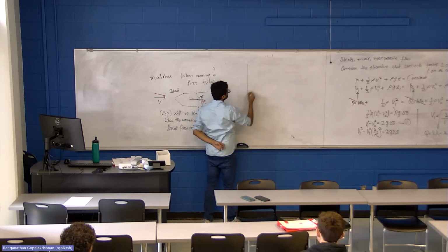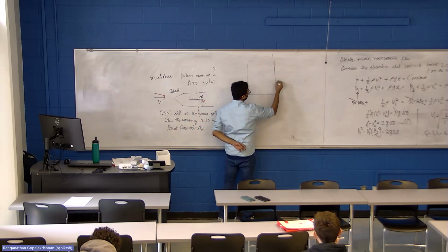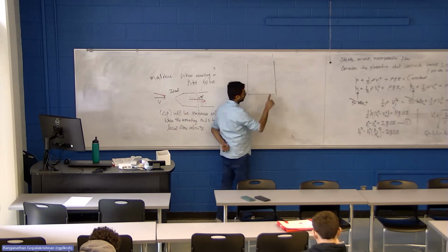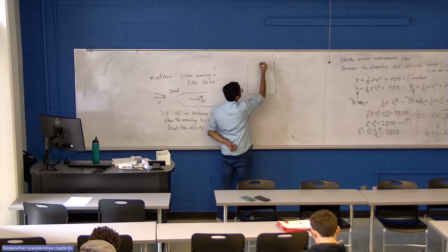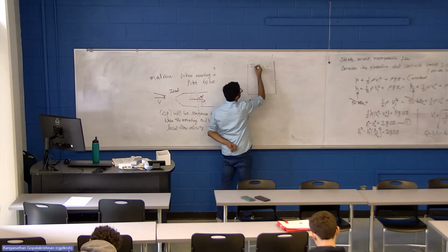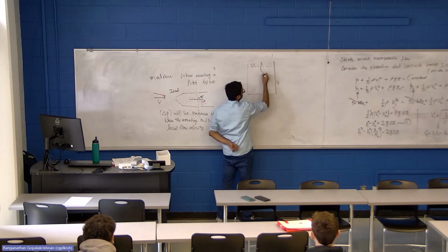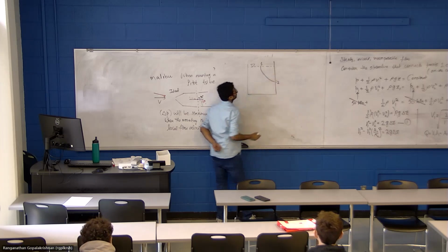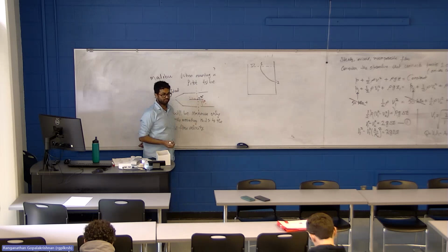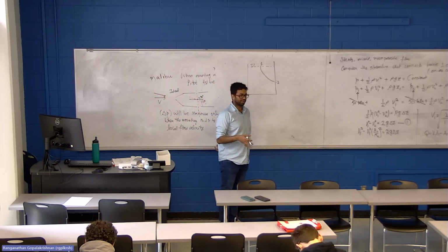So we have our tank. And we are only considering one exit, one hole right now. Don't worry about the other. Let's just focus on learning this first. This is the level, and we consider a point 1 here and a point 2 here. And we'll draw a streamline that connects 1 and 2, just to tell ourselves that these two have to be on the same streamline.